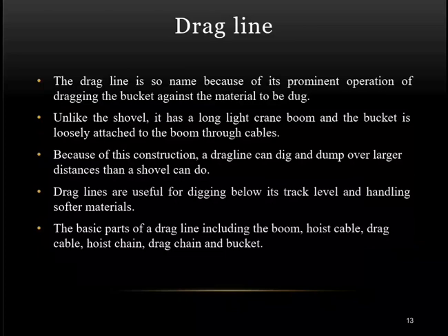Next one is the dragline. The dragline is so named because of its prominent operation of dragging the bucket against the material to be dug. Unlike the shovel, it has a long light crane boom and the bucket is loosely attached to the boom through cables. Because of its construction, a dragline can dig and dump over larger distances than a shovel can do. Draglines are useful for digging below their track level and handling softer materials.